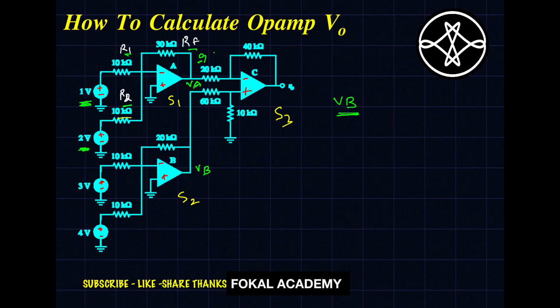Okay, so VB equals the voltage drop here due to 3 volts, that is 3 into minus RF by R1, where feedback is RF, that is 20k. This is R1 for 3 volts and this is another R1 for 4 volts. Let's consider it is R2. So 3 into minus RF by R1, that is 20k by 10k,